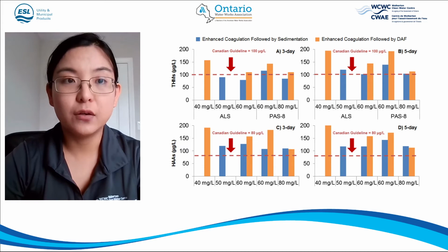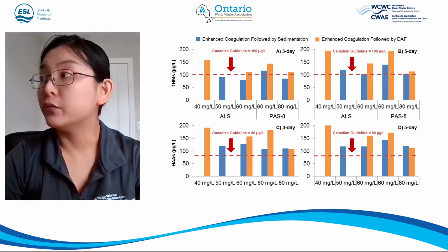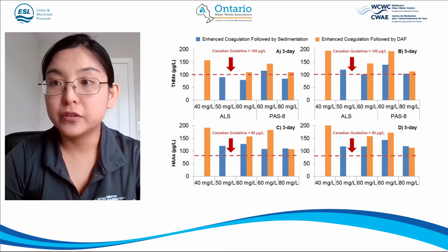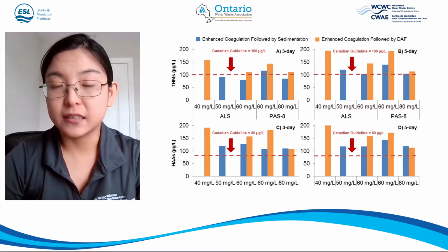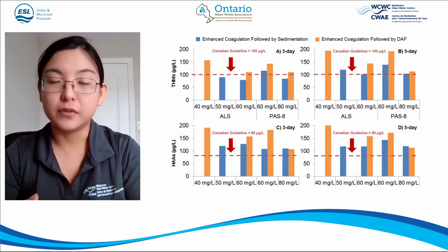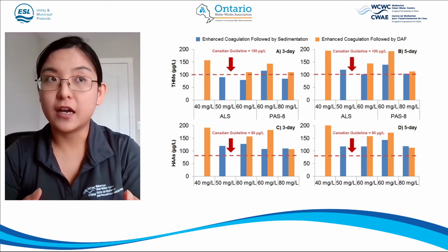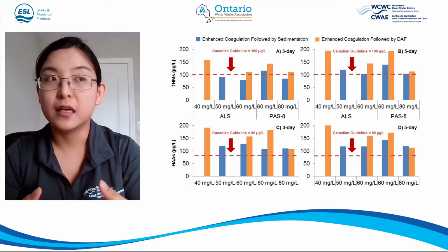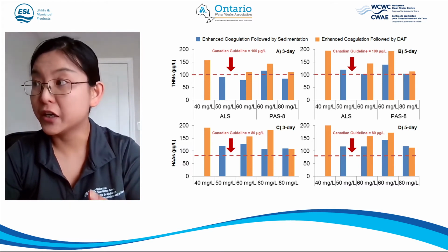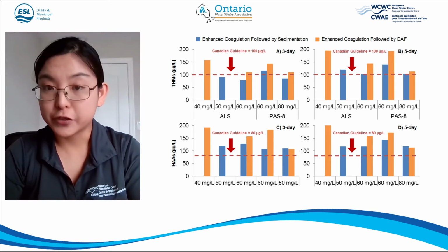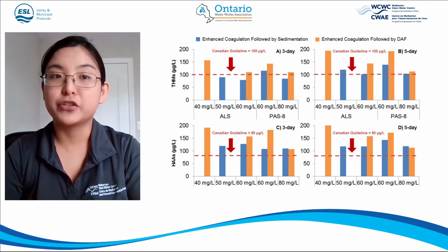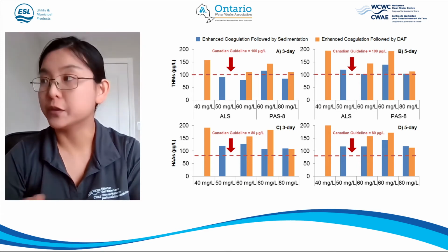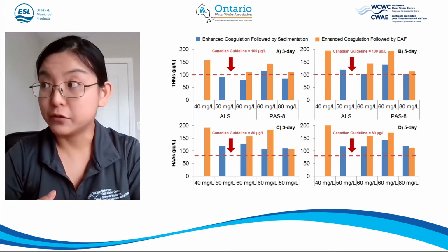So in this case, we dose chlorine at 7 milligrams per liter, which is a relatively high dose. The reason we want to choose that is we know their DOC level was a little high to start with, and also we want to get the highest formation potential to get the maximum formation of TCHM. That's why we dose a little higher. However, chlorine residual after the whole test was much lower than 2. So that means we could also drop the chlorine dose afterwards. But this is just giving us the worst case scenario.